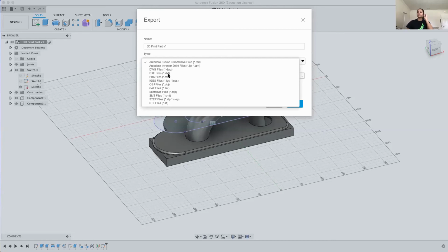So you won't be able to export a 3D printed part. You'll choose a face of the part that you want to turn into a sketch, and you can save that. OBJ and STL are both 3D model files. You would plug those into 3D printer software that slices it all up. But essentially, this is your export format if you want to 3D print something. And a STEP file is a really universal file format that works in every single type of CAD software.